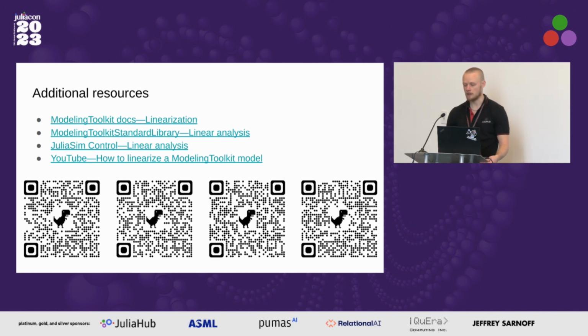And ModelingToolkit is an acausal modeling language, so it doesn't actually care about inputs and outputs. But there is a particular sub-library in ModelingToolkitStandardLibrary that implements blocks that actually are causal. A PI controller is causal. It has an input and it has an output. So that's why it belongs there.